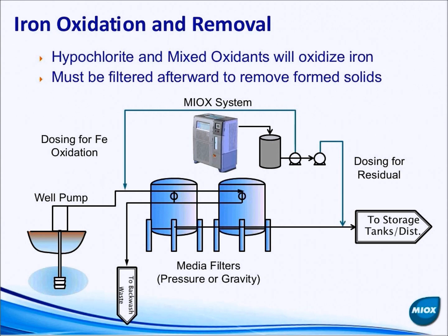You may be site constrained on space. You may just have a personal preference for whether you like closed tanks or open tanks. There's a whole variety of reasons that one might choose one over the other. But you will use a granular media filter on a lot of groundwater sources. This may just simply be loaded with 24 inches of sand media. You may, in some cases, go with dual media as well if that tends to be your preference.